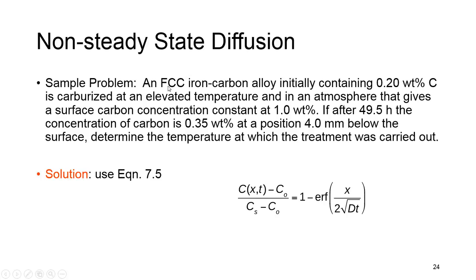So we go to table 7.2, which has diffusion data, and you see the second row is diffusion of C into Fe with gamma phase or FCC. The values of D0 and activation energy can be found from here. D0 is 2.3